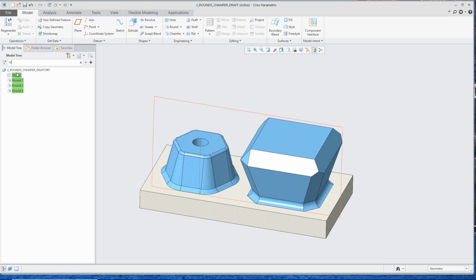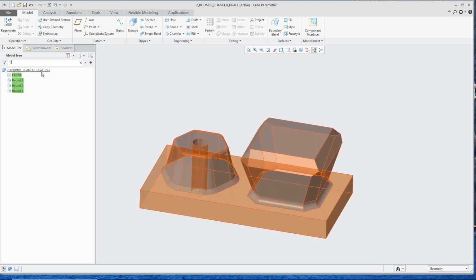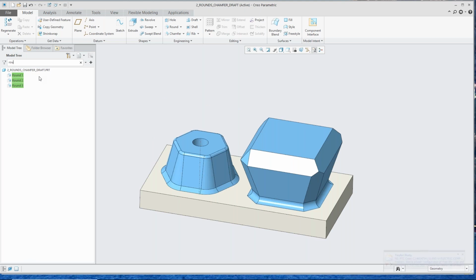And speaking of types, in this case, we have some datum planes. So I can pick on a datum plane here. And you notice now, in previous releases, there's always just a show or a hide. So I can say, turn on that datum plane, like we could always do. But another thing I can do is say, show everything except that datum plane. When I do that, all datum planes are turned on, made visible, except the one that I selected.